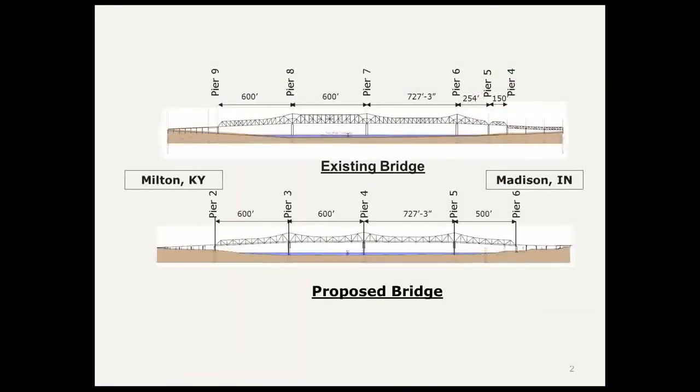So to review what's been talked about earlier, the existing bridge was supported by 5 river piers. And Baker did preliminary work on those piers, and the decision was made prior to our involvement that we were going to save 4 of those piers and demolish Pier 5, the existing Pier 5, which was chloride contaminated.